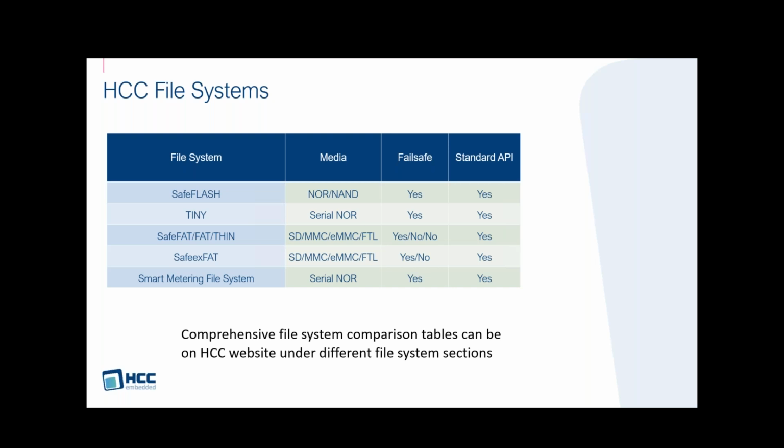and improving the access to the flash by maybe an order of magnitude in different use cases, which can reduce the cost and the wear on flash devices. This means if you're making a meter for long endurance or a data logger for long endurance, you can reduce the size of flash required, cutting cost. You can also model it very easily and have a much more focused solution for the purpose of doing data logging. And that's a very specialist application of a file system / database access method for managing flash that gets the very best in terms of cost and performance out of your flash device.